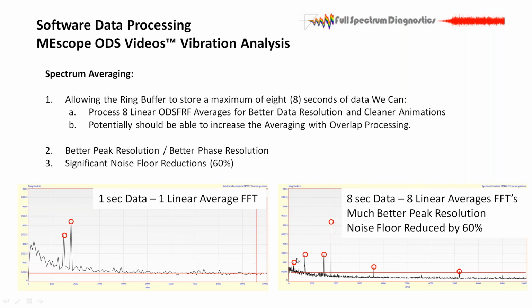But I missed all this. I missed 4 peaks out of 6 because they're overwhelmed in the low frequency end, and they're swept up by the noise floor in the high frequency end. Now I have a red line here. This is basically the baseline of the noise floor, and I left it in there for this one.